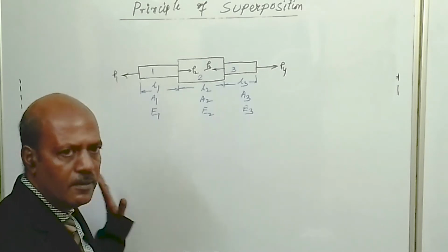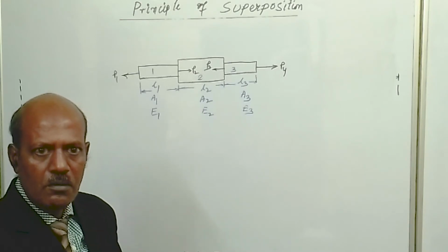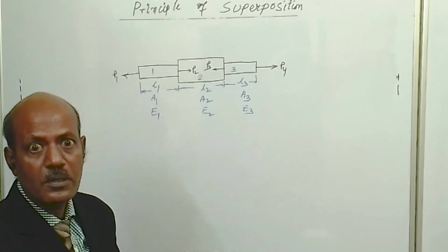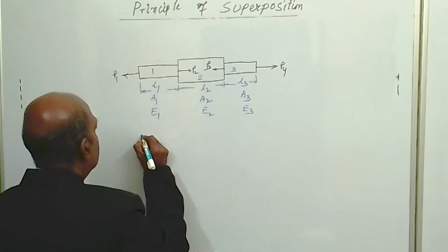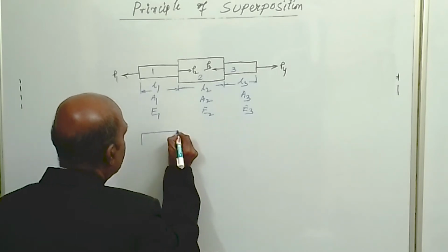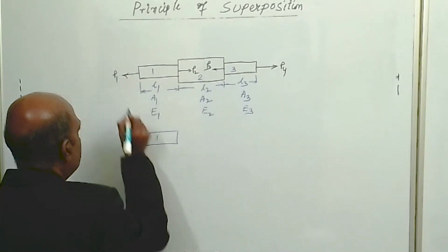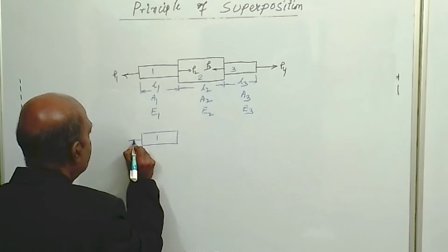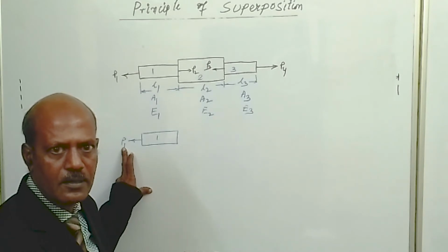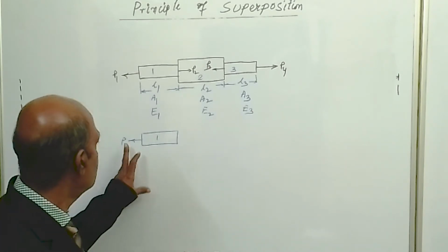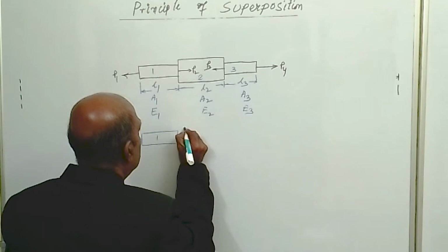So this much is given, but in the first step we are going to draw the free body diagram to see what is the exact force acting in different segments. Okay, so if we draw the first section, so this is the first section. In this it is seen that P1 load is acting towards left. So what is the kind of load acting on segment 1? That is tensile load. If on this side P1 load is acting, then on this side also it will be P1 load.